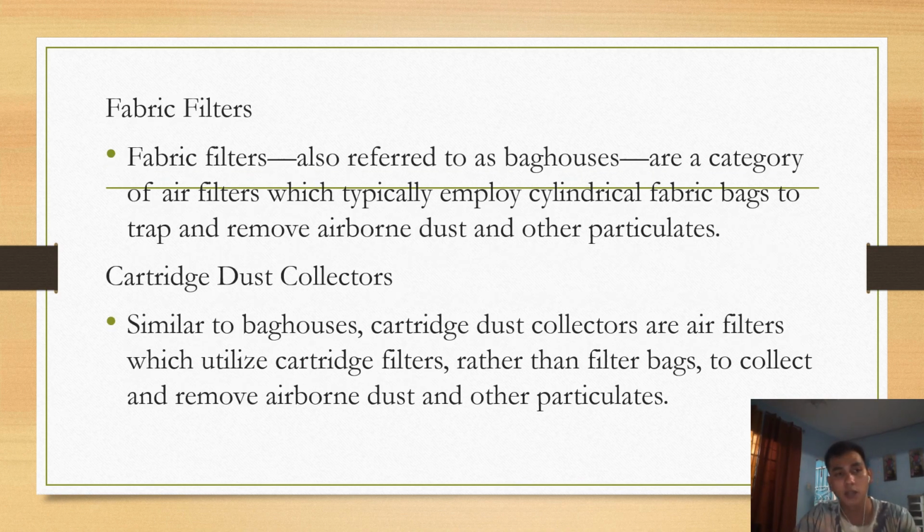Cartridge dust collectors. Similar to baghouses, cartridge dust collectors are air filters which utilize cartridge filters rather than filter bags to collect and remove airborne dust and other particulates. The particulate accumulation on cartridge dust collectors also requires periodic cleaning and removal. While this type of dust collector can attain higher efficiencies than a comparable baghouse depending on the cartridge material, it can also be more sensitive to condensation.